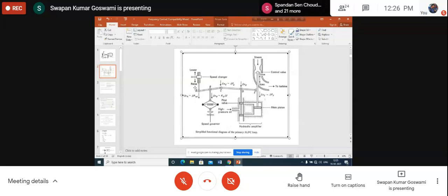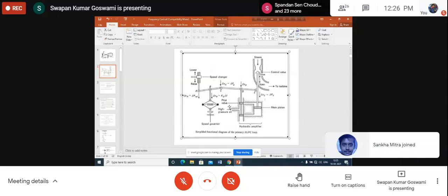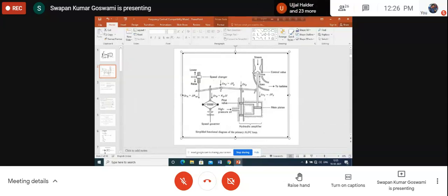And when you give a power increase command, as we have discussed previously, using the same process, the power output will be increased by the generator. Okay, so this is how the speed governing mechanism actually functions. Basically, following a power increase or power decrease command, there will be some momentary change in the speed of the synchronous generator. That's why it is called the speed changer.